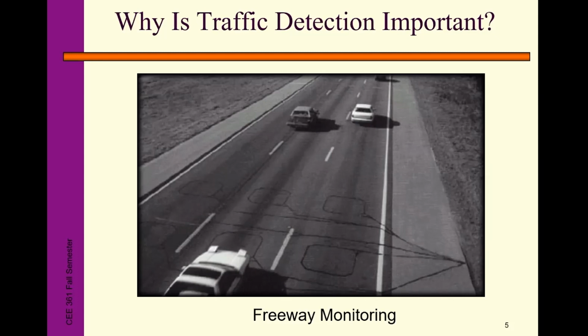This dual loop sensor produces the ideal traffic performance measurements we want, such as vehicle volume, density, speed, and vehicle length. We want to know how many large trucks are there rather than small passenger cars, because the congestion impact generated by different types of vehicles is different. So we use the dual loop sensor to measure the traffic condition in real time.